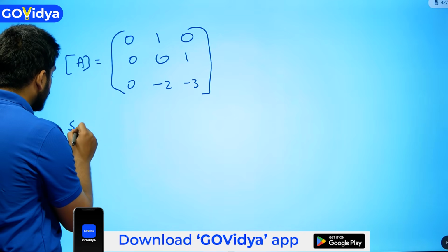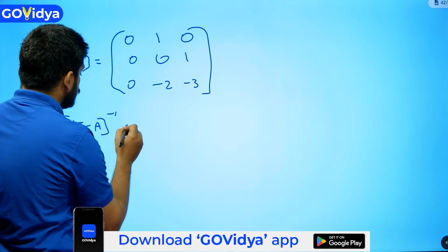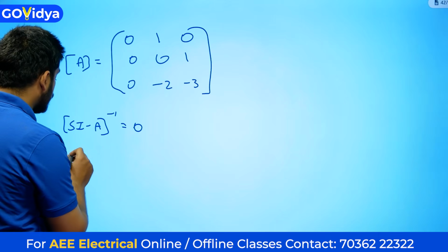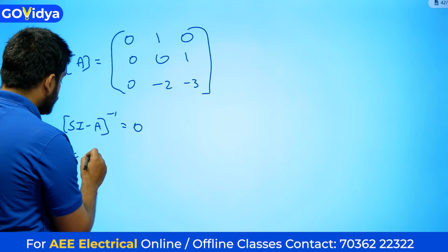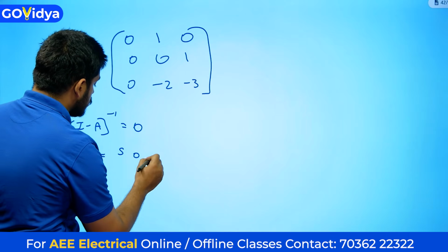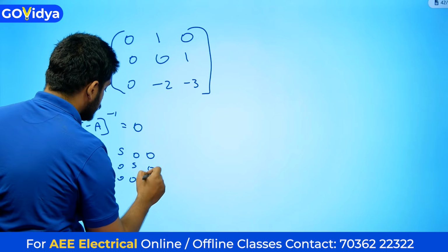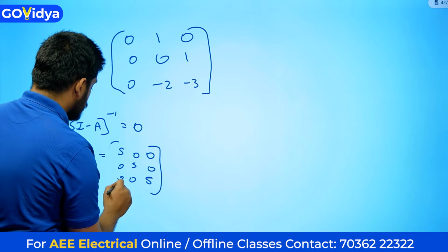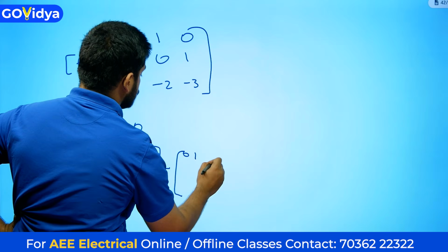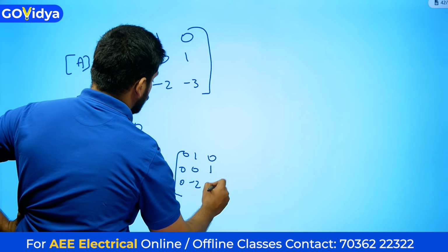What is the formula for finding eigenvalues? Det of (sI minus A) should be equated to 0. Okay, so what is my sI minus A? Firstly, sI minus A would be [s 0 0; 0 s 0; 0 0 s] minus [0 1 0; 0 0 1; 0 -2 -3].